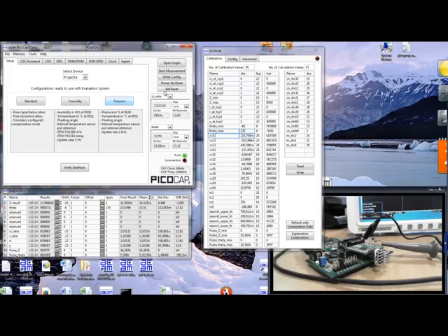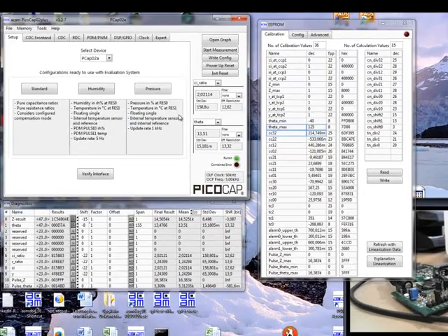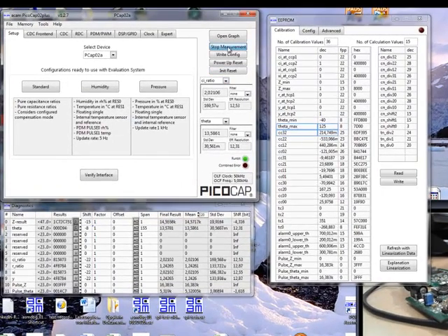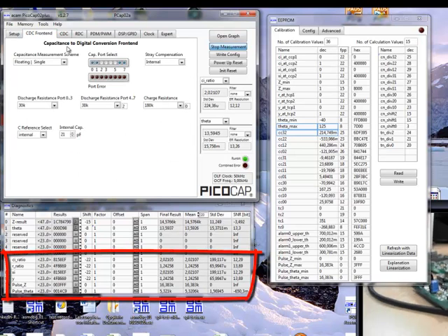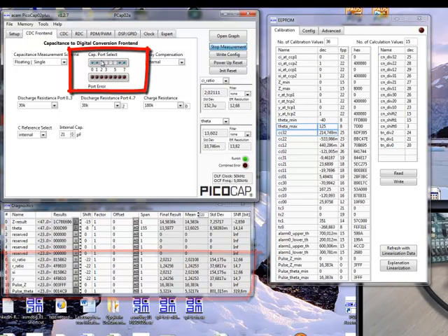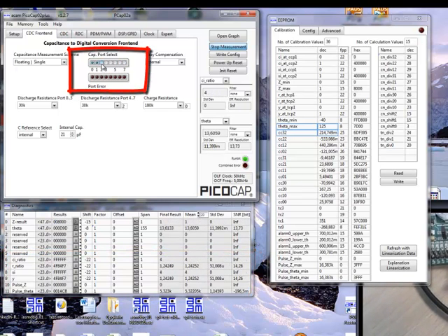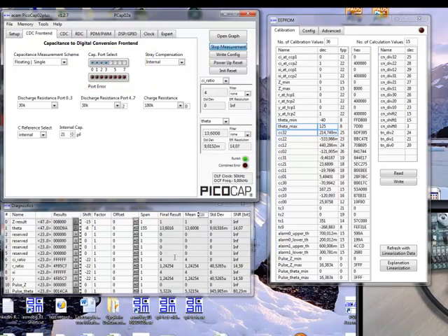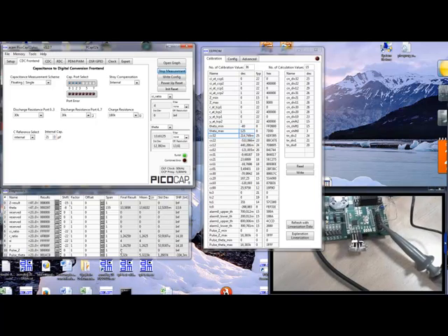So now I'm starting again the measurement by clicking Init Reset, Write Config and Start Measurement, and have a look at the results we get down here in the CI ratio and the other parameters here. What I recognize is that not the right capacitive ports of the PCAP02 are selected, so I need to select from 0 to 3 here to reflect the two floating capacities I have connected.